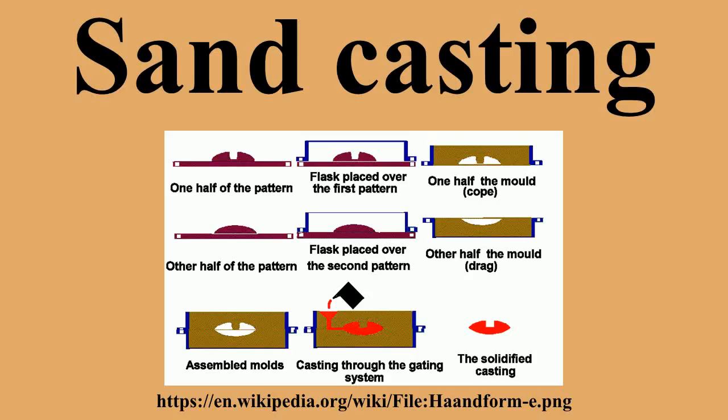Negative forms are used to produce cores. Usually sand-molded cores are inserted into the casting box after removal of the pattern. Whenever possible, designs are made that avoid the use of cores, due to the additional setup time and thus greater cost. With a completed mold at the appropriate moisture content, the box containing the sand mold is then positioned for